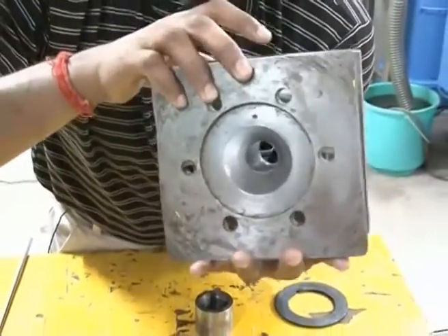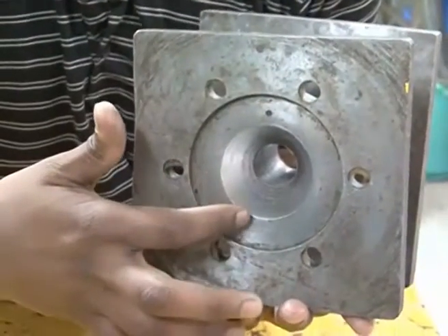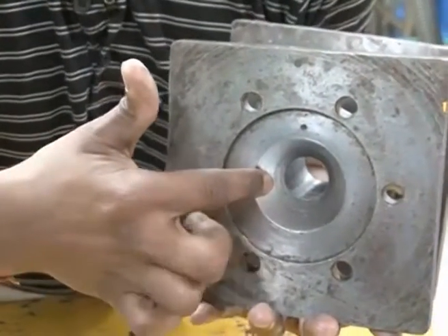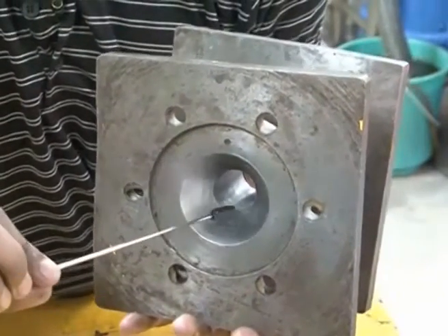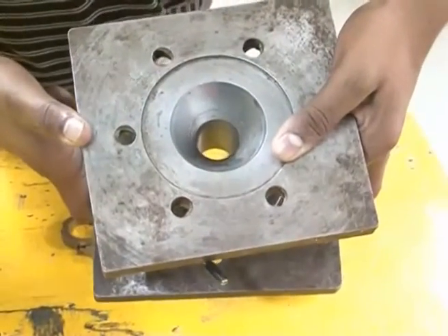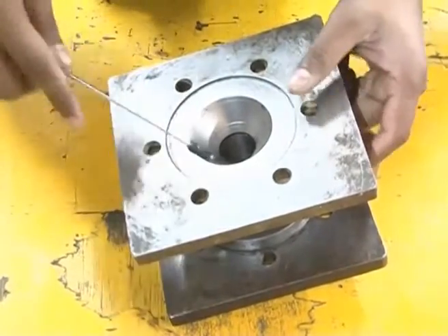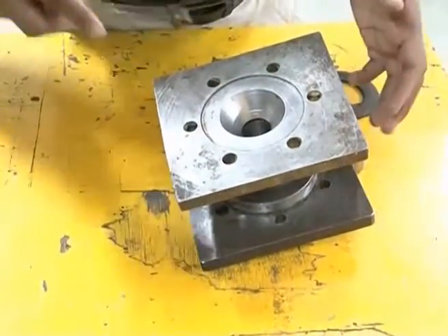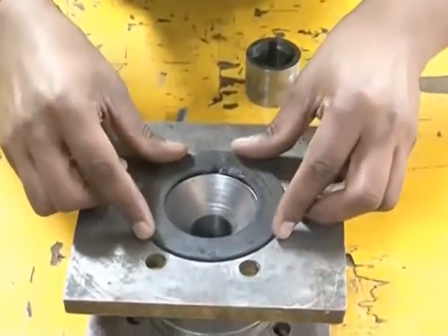And you can see this tapered portion. This hole size is equivalent to the bottom medium cylinder hole, and this medium, when comes here, it gradually flows through a tapered portion and it enters into the workpiece region and comes out from again a tapered portion. This is again equivalent to the top medium cylinder size, and it goes into the top medium cylinder. Similarly, every cycle takes place. And additionally, we have a washer to control the leak.